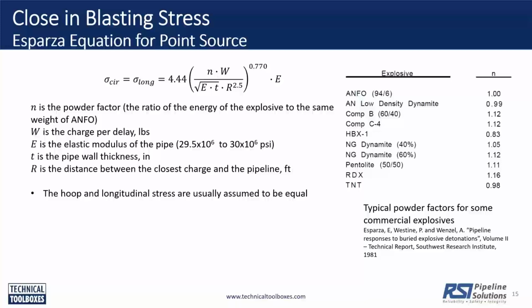That's a famous criterion that they use. Sometimes they say 1 inch per second if you're in a city. If you are near an architectural monument, they say it's ½ inch per second because older monuments and structures are more sensitive to cracking. All those limits, when they say 2 inches per second, 1 inch per second, ½ inch per second, are meant